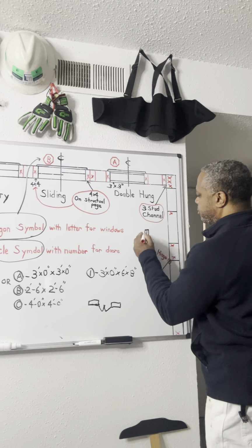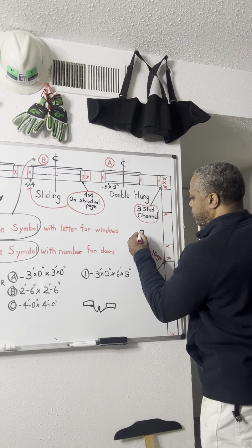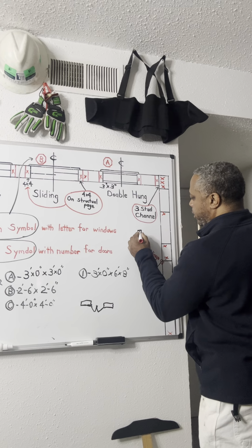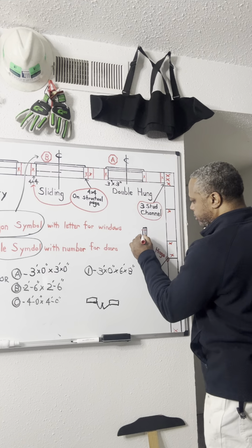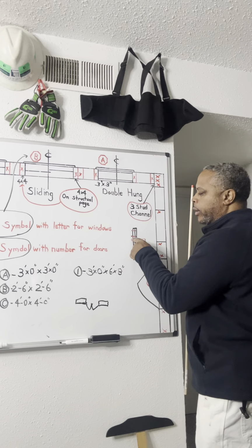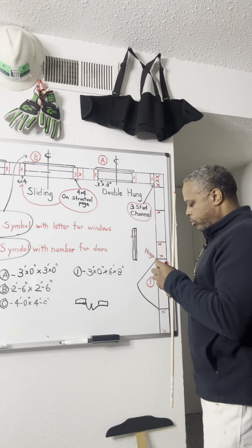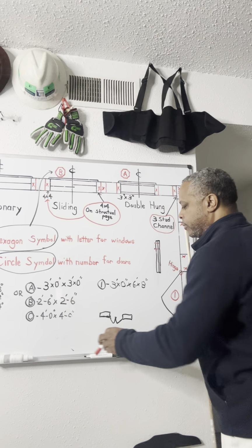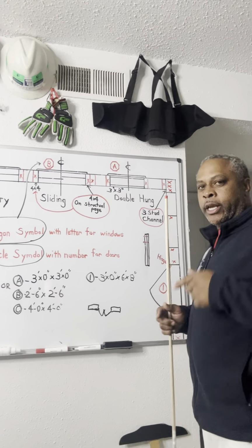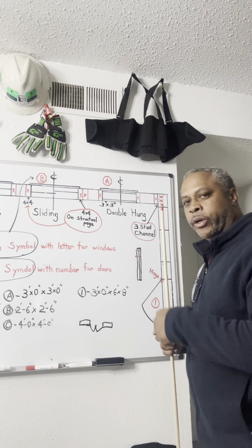Nails are going to be driven into one to the other. Nail's going to penetrate one through the other. The nail head is not going to stick out like that. So don't think that the nail head is supposed to stick out. Drive the nail in. This is rough framing. You have to drive it. It can penetrate through the wood.